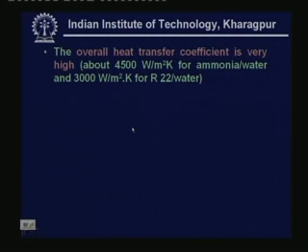And the overall heat transfer coefficient in a plate type evaporator is very large. You get about 4500 watt per meter square Kelvin for ammonia-water and 3000 watt per meter square Kelvin for R22-water.